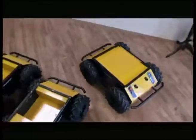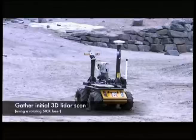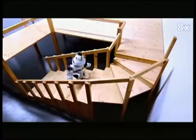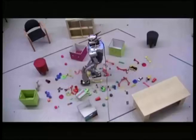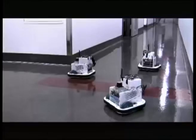So oftentimes what's happening on these platforms is there is a real-time layer operating beneath ROS. Like they discussed on the Nao, there's an RTOS and a different processor that's running, but ROS can sit on top and help with the perceptual systems that are quite general and applicable to many different robots. So some of these kinematics are wildly different, like that platform. There's a Nao with a laser on its head, and then this is doing more footstep planning. Again, ROS isn't running on the Nao, it's sitting on top and being bridged to it using the layer they described.